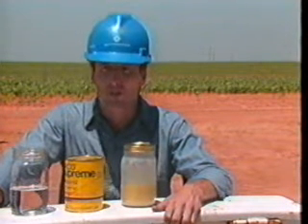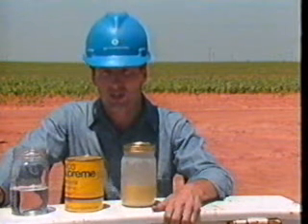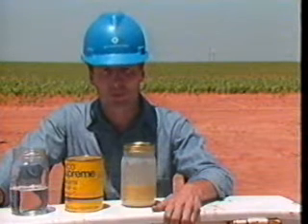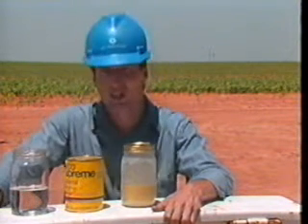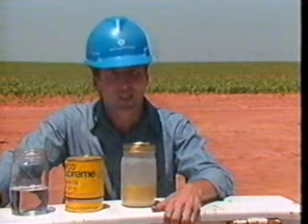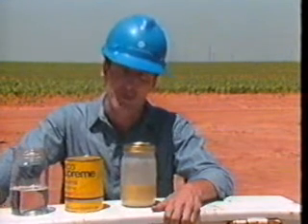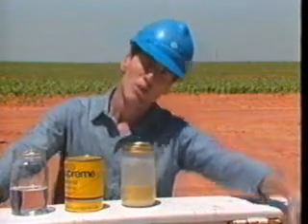Now, some emulsions can be adequately treated through settling alone. Tighter emulsions need additional treatment procedures designed to speed up settling. The ideal way to treat oil is without heat, but treatment frequently requires heat to speed up separation. Let me show you what I mean.